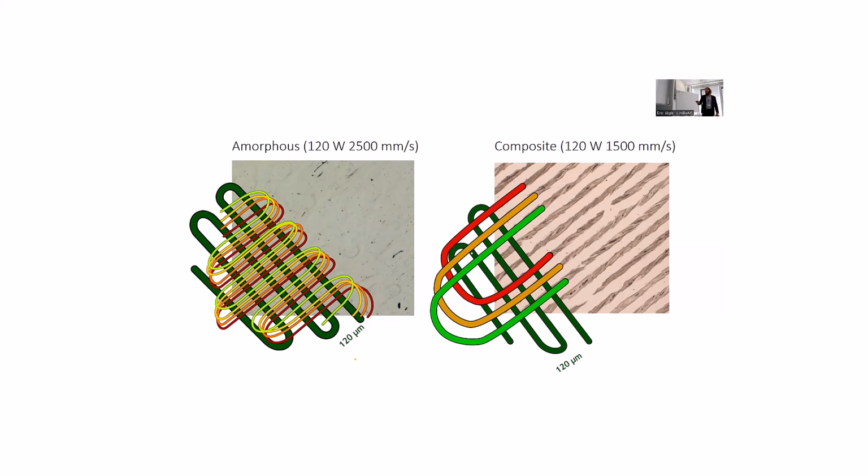In this case, I'm making several scans, each around 300 microns from each other. I put four models: one for pre-melting, just to get rid of the powder, and then for the next ones I separate hatches by 300 microns. You can see right now this green light, I go this way. Then those are at quite a distance. Then I go to the next line, and the next line. So I melt it actually in a few passes. Then I can really do whatever I want with the microstructure.